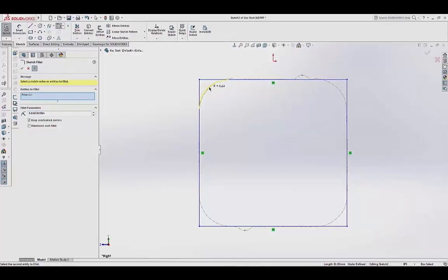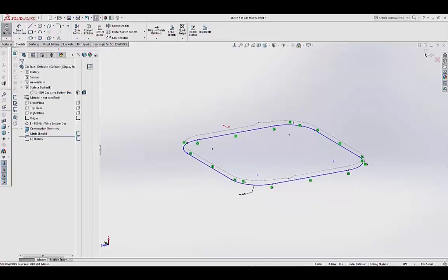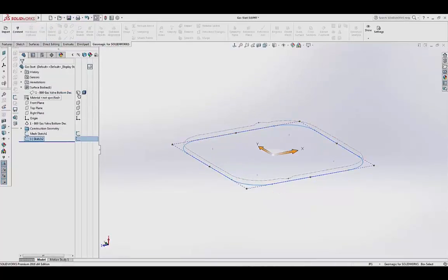So you see here that if I just grab and create some fillets, I'm able to determine what radius that fillet is just by visually looking at it. And then I can override and say, okay, that's a 0.65 of an inch radius, and apply that and create a nice, beautiful cross section from that scan data.